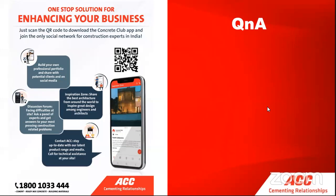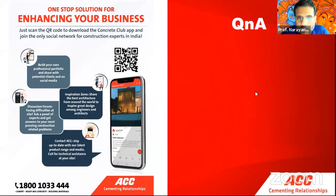The first question, shall we use glass powder in UHPC? Absolutely, you can use glass powder in UHPC. The only thing that you have to be very careful about when you use glass powder is that its behavior in concrete is a large function of the size of the glass powder. So if you have not ground the glass powder really, really fine, you are exposing your concrete to potential alkali silica reaction. So that has to be carefully taken care of. But if you have a very finely ground glass powder, you should be good.